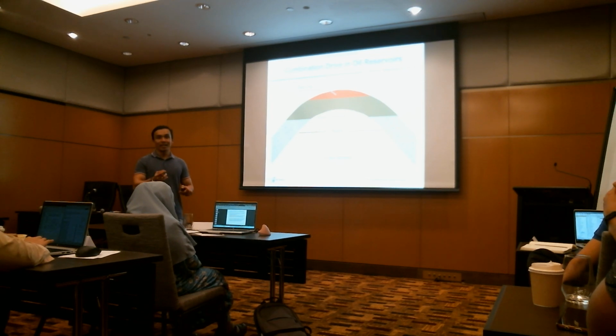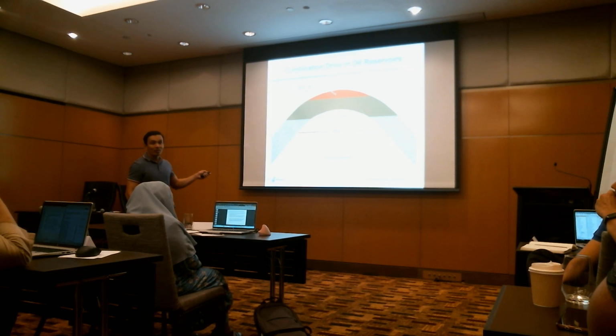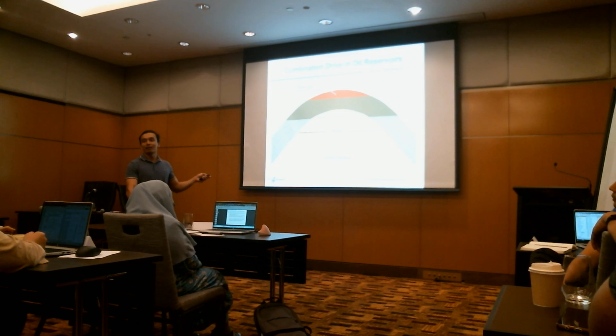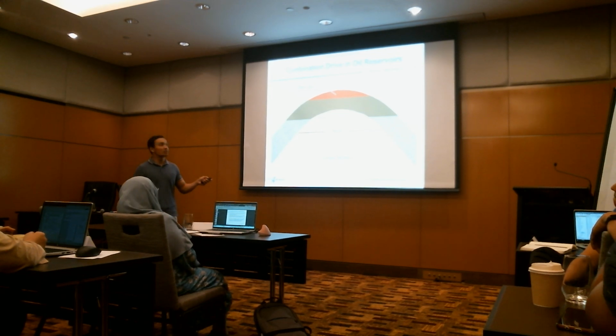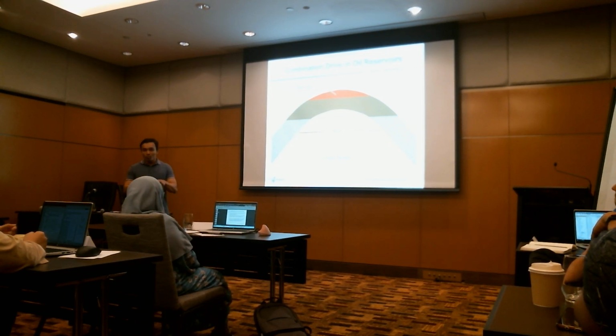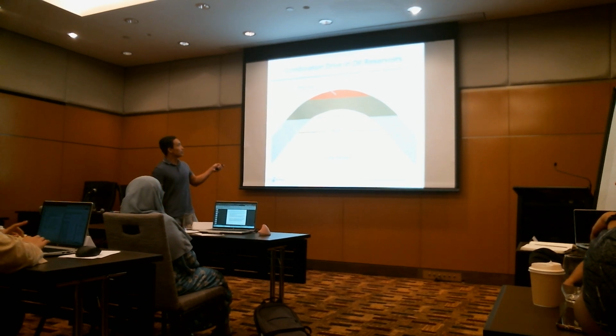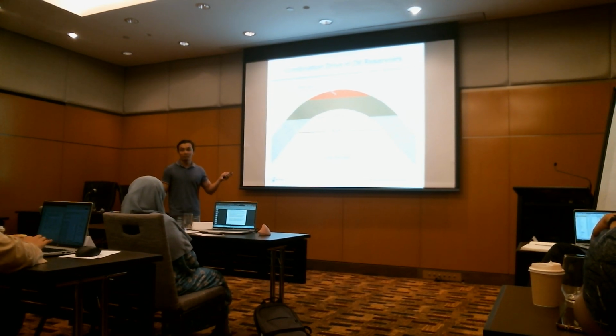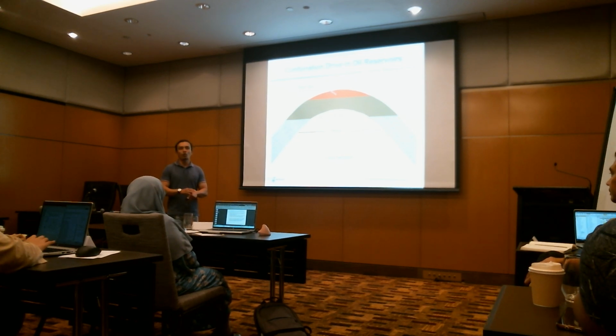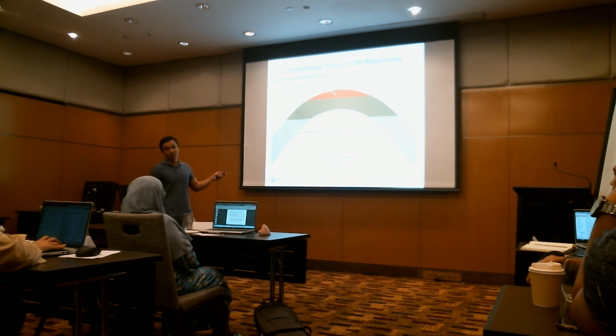That's one thing. The second thing, I think the most important, is that this is your energy, right? You don't want to drain your energy, otherwise you will strand your oil there. So as much as possible, you want to control your gas so that you blow down later. Normally, we do that towards the end, when there is no more recovery from oil, and then you blow down the gas.